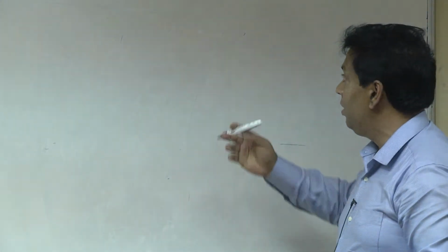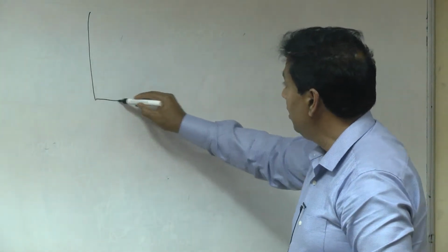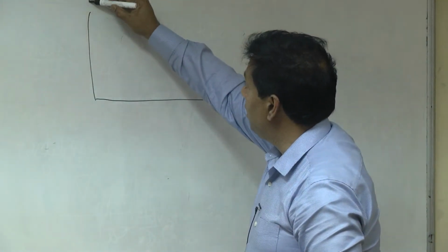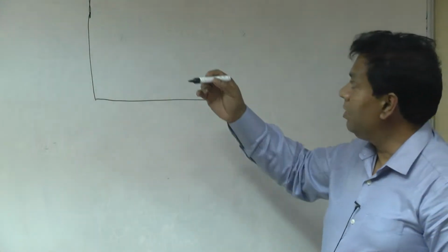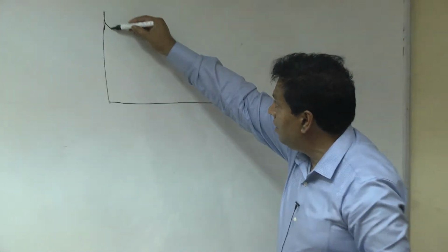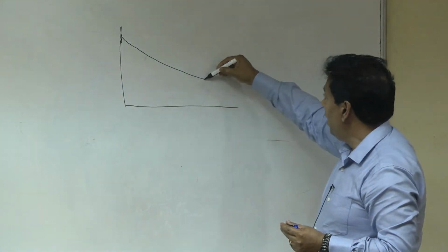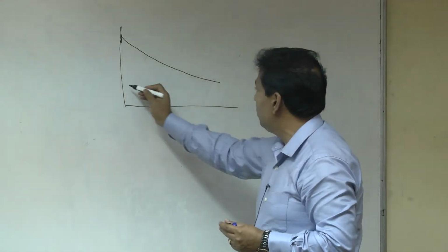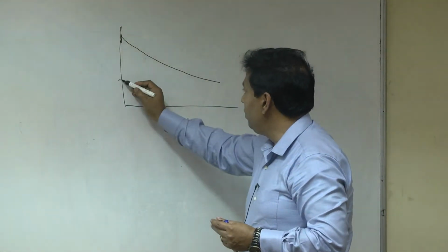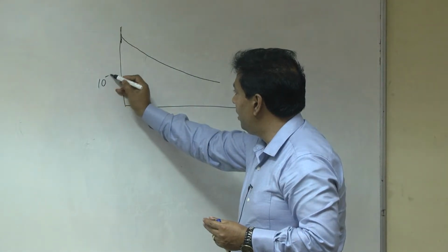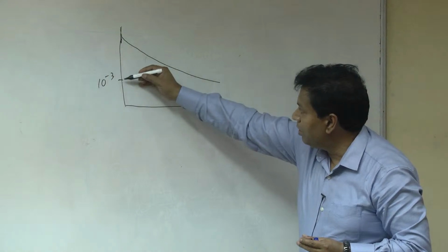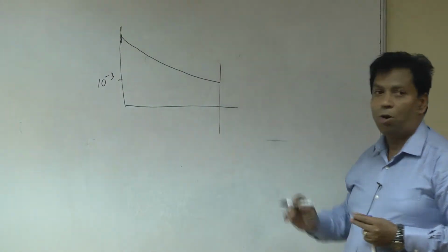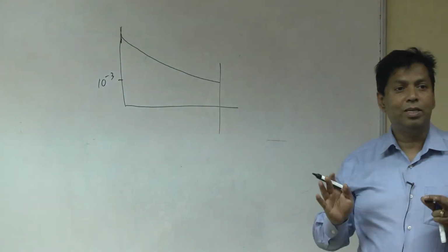One thing is from steady state. Yesterday you did the steady state. For the steady state, what did you see? You see all the continuity, the momentum, okay? All the residuals were coming down like this, right? And after a certain time, when it reached the residual value we chose, like 10 to the power minus 3, all the equations come down to 10 to the power minus 3, then the solution is stopped. Okay? That means the solution converges.